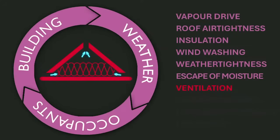Traditionally, roofs of all kinds required ventilation to ensure moisture could escape, as bitumen felt underlays did not allow moisture transfer to any significant extent. Whilst there's nothing wrong with this approach and it's been used successfully for a very long time, as buildings become increasingly well sealed and moisture loadings increase, it's not always optimal. This is particularly the case where complex roof shapes and rooms in the roof are present, creating the potential for dead spots where air cannot properly circulate, leading to localised damp and mould.